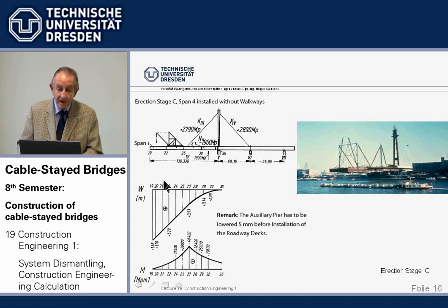Well, considerable length means 1.88 meters against the final stage is a deflection, nearly 2 meters down here. Wow, that's what I call considerable, huh? Because we have this long cantilever. Of course, we have a heavy moment, but apparently that's in the range or needed little reinforcement for this stage.